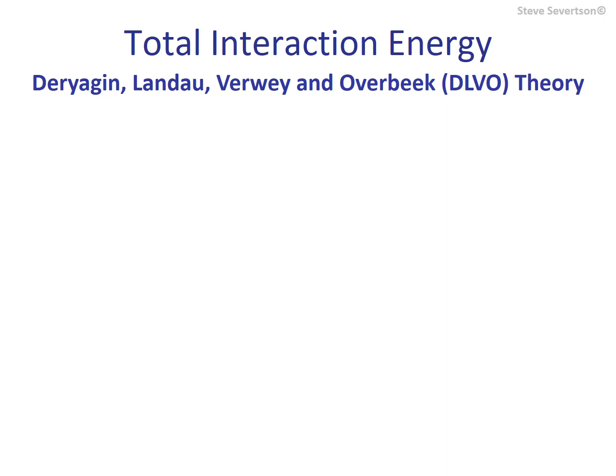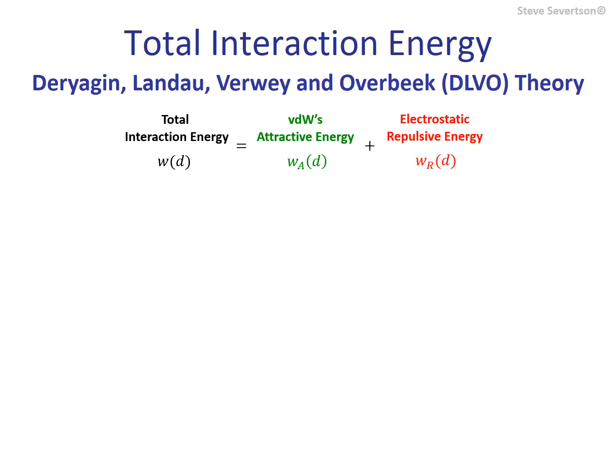For now, let's restrict our discussion to van der Waals attraction and electrostatic repulsion between particles, and we will switch from considering interacting infinite plates and consider interacting spheres. Although particles and solids can take on a variety of shapes, including plates, for emulsions and even foams, the particles tend to be spherical or roughly spherical. The idea that van der Waals and electric double layer interactions between particles are additive was proposed independently by two parties of scientists, the Russians Derjaguin and Landau, and the Dutch scientists Verwey and Overbeek. Their theory is more commonly known by the abbreviation DLVO.